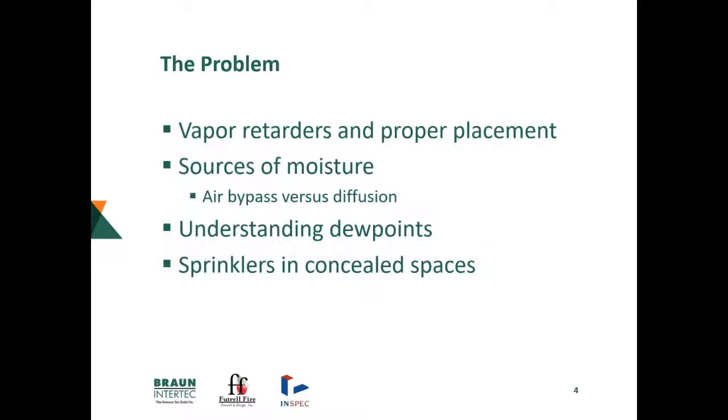Part of the thing we're trying to do here with the seminar is also get you used to understanding more about dew points, get into a little bit of research on it on your own, learn about that, learn about the WUFI modeling, which will help take your local weather conditions into account over a 5-year period and look at how the moisture may continue to build up in the systems. The failures we're seeing of these roof decks is occurring anywhere from 2 to 10 years after completion of the building. We're going to see a lot more of them. There's more and more of them showing up every day.